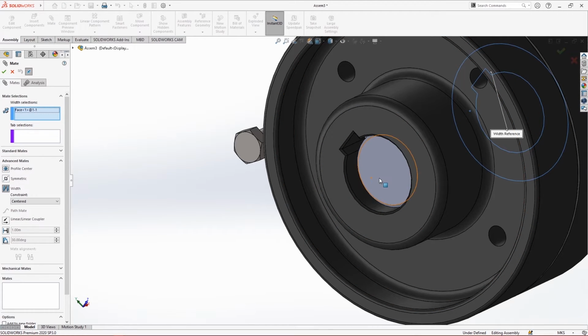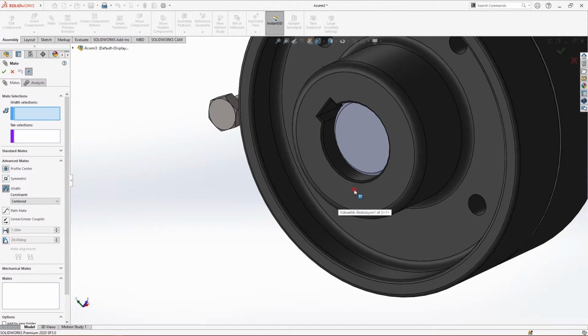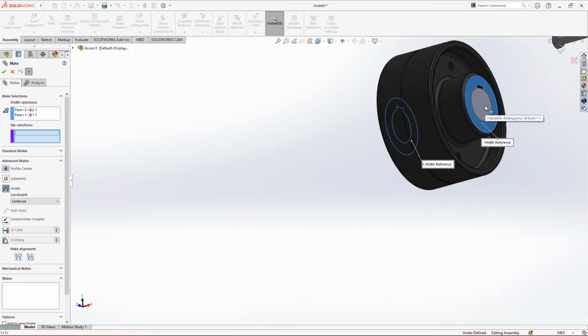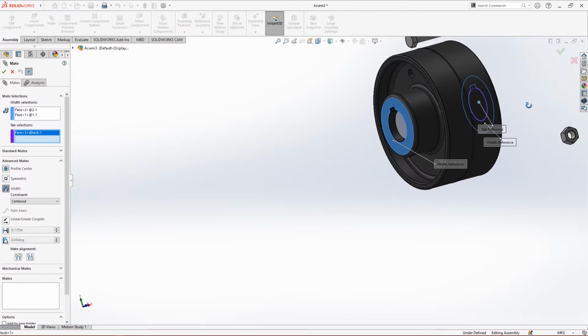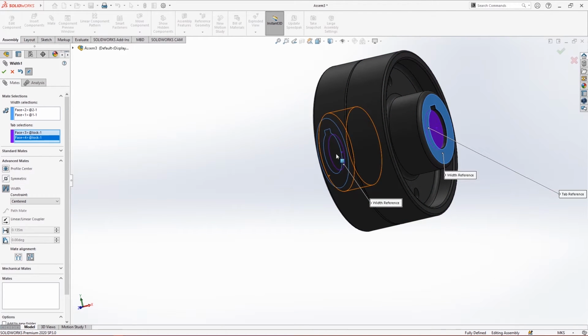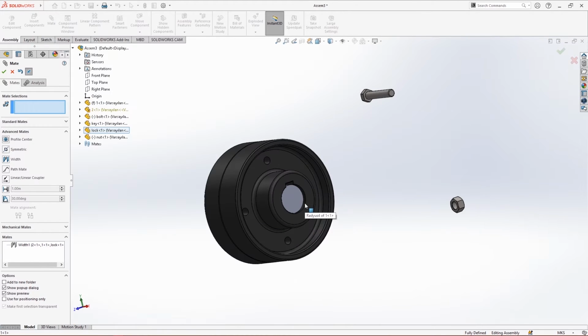So in width, what it does is a great help in centering purposes. So what I do, I just select this plane as a width, this and this one, and these two as a tab, and it will center it. And you can see it does a little shift and it is in center. So you can also do other things, but it is really good for the center purpose. Now you can see it is in center.